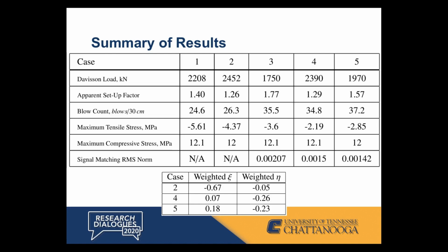This stratigraphy looked more cohesive to the pile than the borings would indicate, which indicates that the xi and eta, which are strictly set up based on typical values, may need some adjustments in the way we do forward methods.